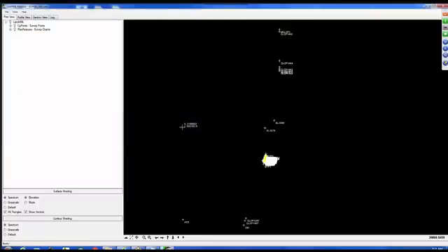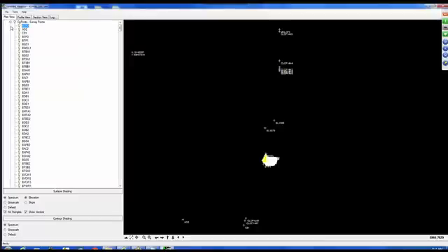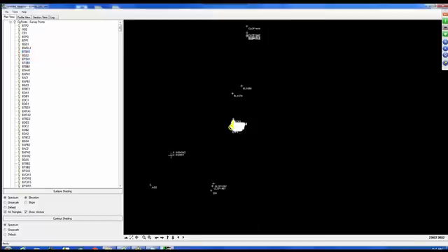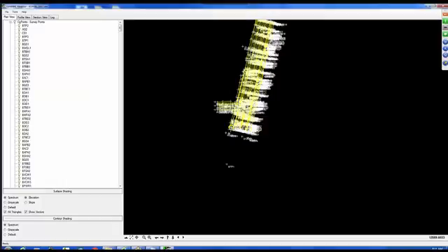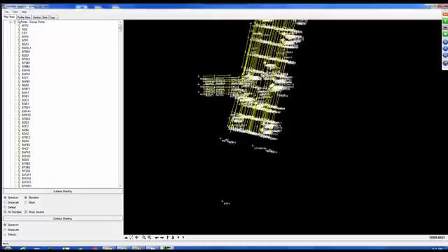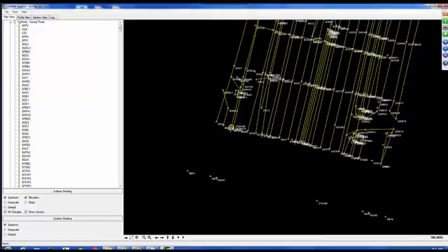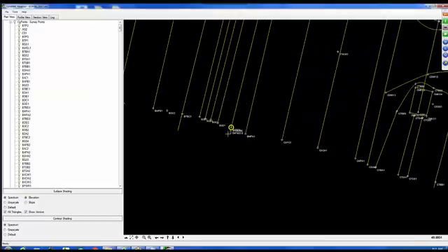So you can see on the screen we've got some graphics now. Now, if we look over here in the Plan View tab, you'll see that we've got two groups. We've got our COGO points, which is our survey points, and we've got our plan features, which is our survey chains. So let's take a look at the COGO points first. So these are just our plain survey points. So if I pick on any one of these points and I right-click, I can pick on the option Center On. Okay? And it will center the screen to where that point is. If I use my scroll wheel on my mouse and push it up, I can zoom in to that particular point. Let's pick another point. Right-click, Center On, and it just allows me to bounce around the drawing and just look at the data.